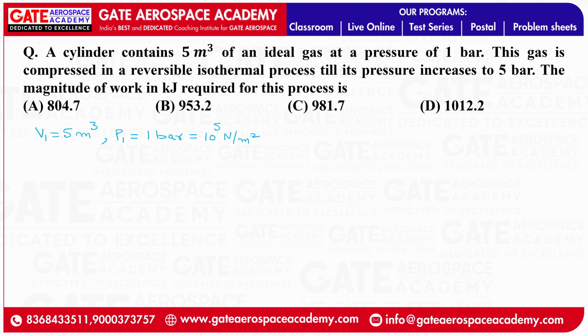The gas is compressed in a reversible isothermal process till its pressure increases to 5 bar. So we are compressing the gas by an isothermal process. So P2 will be 5 bar, that is 5 into 10 raised to power 5 Newton per meter square. Newton per meter square or Pascal is the SI unit of pressure.